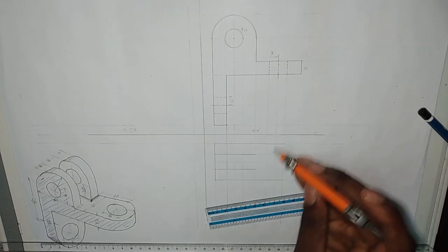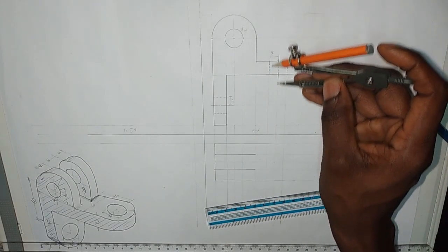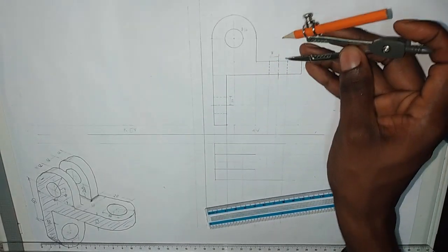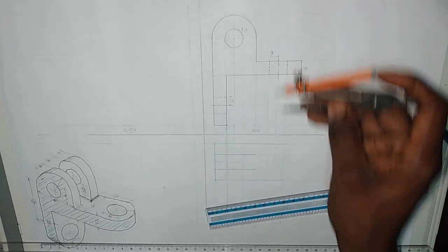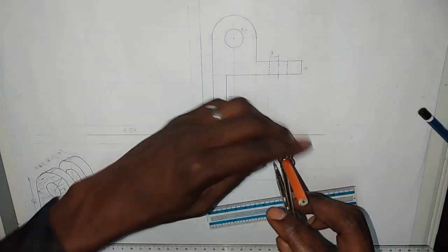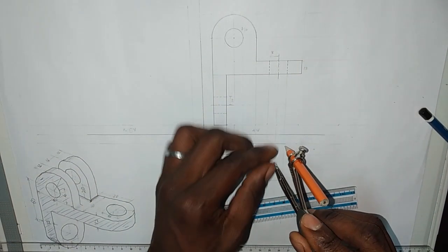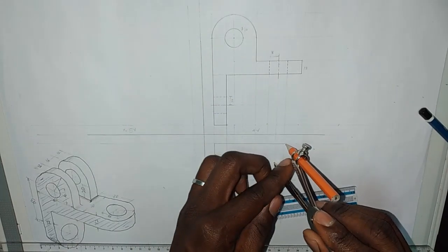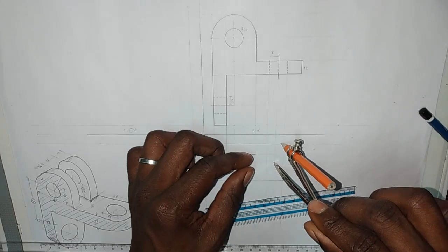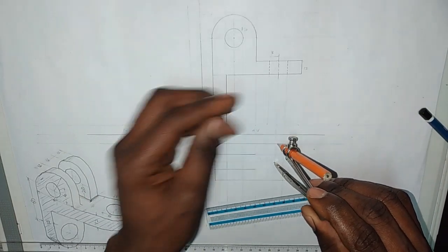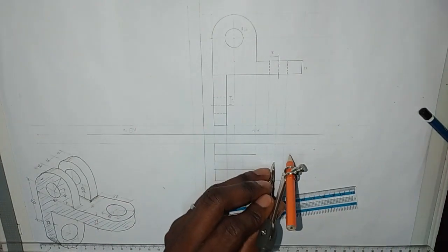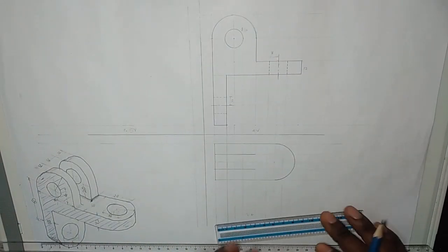of the plan. We are going to stand at where that line intersects the projection from the center of the hole in the front view. So this line intersecting with this one is going to be right here. So I'm going to stand here and draw an arc. That arc is actually tangent to here and this other one. Sorry, it's tangent to here, this point, and then this point. I'm going to draw that arc. So I have my arc now.